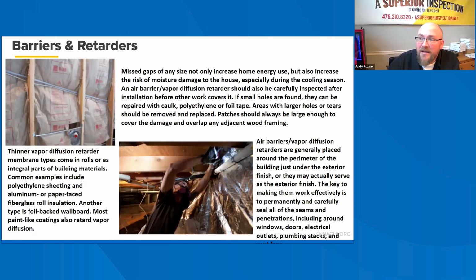A home may not need a more effective vapor diffusion retarder than the numerous layers of paint on its walls and ceilings unless it's located in an extreme northern climate. Vapor barrier paints can be an effective option for existing homes in colder climates. The perm rating of the paint should be indicated on the label. Glossy paints are generally more effective vapor diffusion retarders than flat paints, and acrylic paints are generally better than latex paints.